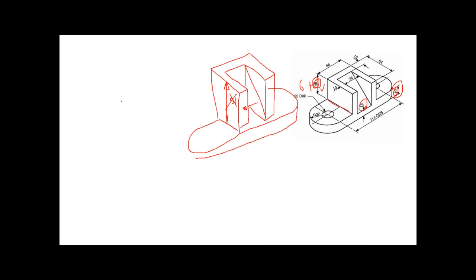So here is the best way, guys, to deal with this problem. You have to draw the base first. Of course, you'll draw it as a 2D, with your X and Y on top, like this. So you draw a very simple two-dimensional surface like this. We can do the box and then fillet. Yes, you can do whatever.